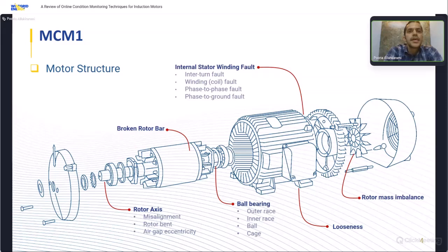And we have the bearings and the cooling system here. You can see if the fan in the cooling system is damaged or the bearings have an alignment issue, we can see the heat goes up in the system. So we need to ensure proper cooling every time during inspection of the motor.